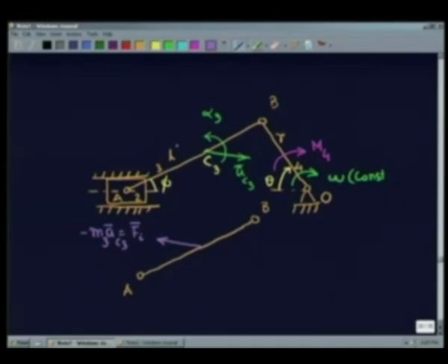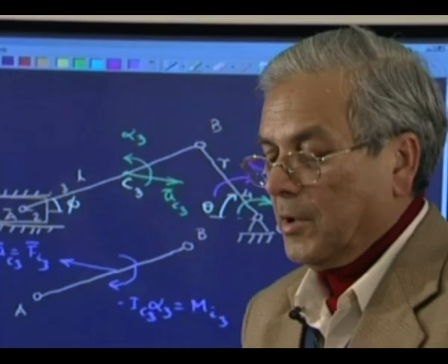We also subject this to inertia torque, which is nothing but minus IC3 alpha 3, which is the inertia torque for link 3, say.